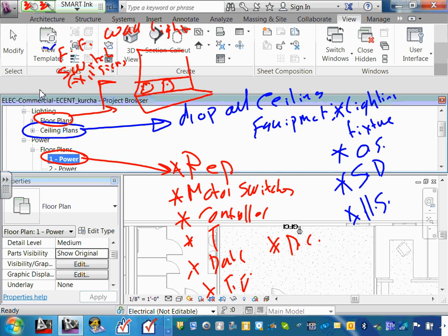Now, so that's basically it. The families have to be hosted. The second thing they have to understand about Revit is families are hostable. They're hostable or non-hostable: things that need a host and things that do not. Like you guys at Michelle, a lot of stuff they use non-hostable ones. They like them because you don't have to worry about where to drop them. So if you have a non-hostable receptacle, literally, and that's the scary thing. If you have a receptacle, they're non-hostable.